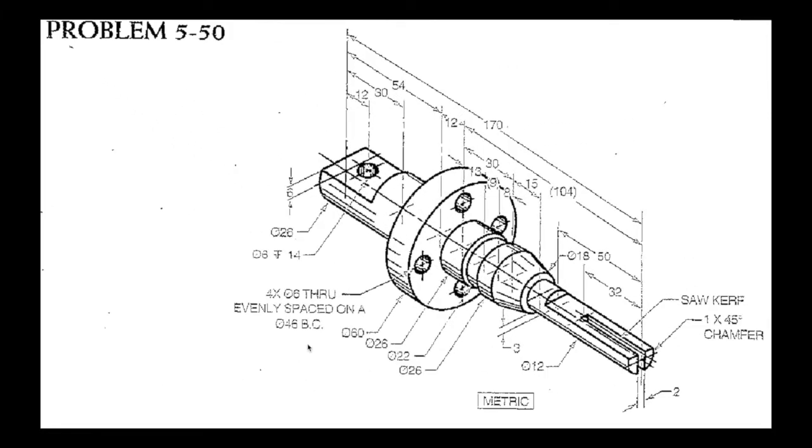I'm going to approach this a little bit differently. I'm not going to approach it like a block of material that I'm cutting out. This would actually be done on some sort of lathe or a CNC mill that has a revolve rotation. So I'm going to be using the revolve command in my CAD, or my Onshape, to make this. What a revolve does is it takes a profile and sweeps it around a center axis at whatever degree.